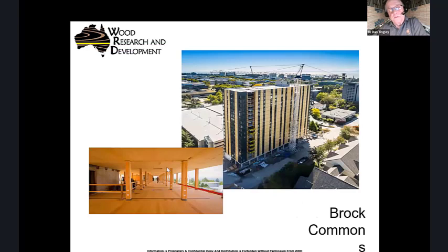We just developed a new test apparatus. You might have followed me on LinkedIn for designing ways of understanding the minor and major axis shear in major panel sizes, 10 by 40 foot long, for example, where we have point loads. We know intuitively that shear is not just 3/2 V/A; it's really a width and length issue, horizontal shear.